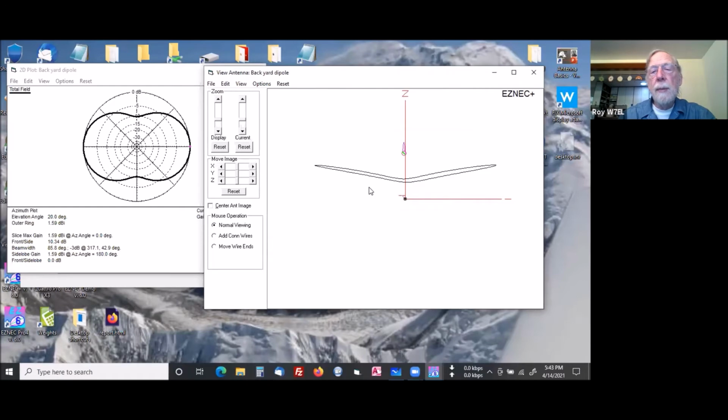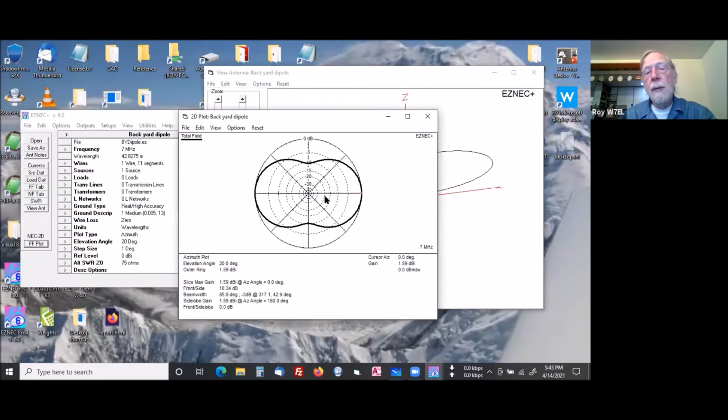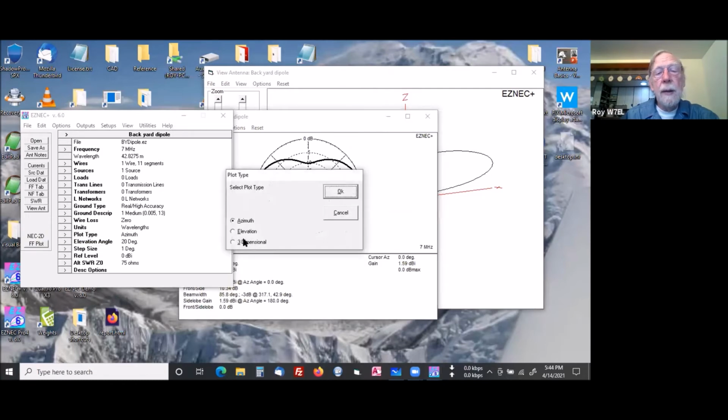You see it's tilted up 20 degrees. So we're looking at the plot up 20 degrees from the horizon. And we know this, in this case, the magic person stays up 20 degrees above the horizon and goes all around the compass, completely around the antenna, staying the same distance away and 20 degrees up. And that's how we generate the horizontal plot. But right now I want to go back to the vertical plot. So we'll go back to elevation.